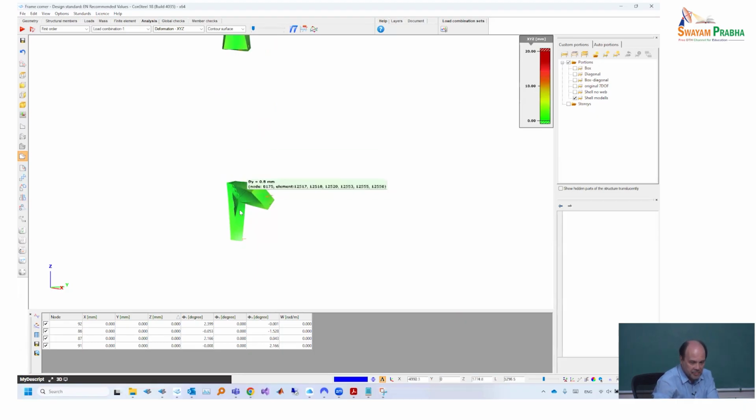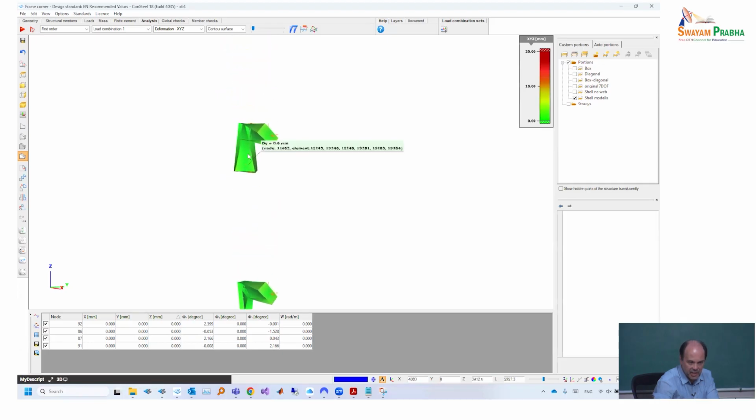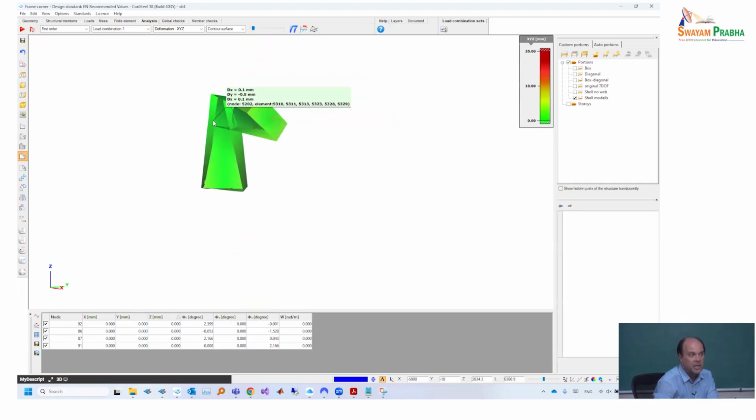So this is what we have, and what is also very important is that this can only happen with serious deformation of the web. So clearly in this zone, the beam element is completely off. It has zero validity. There is a very strong section deformation. It's not warping deformation, but really a very strong web deformation. So if I wanted to describe this with a beam element, then I would need to employ a beam element which is really able to describe web deformation. The 7-degree-of-freedom element cannot do that.